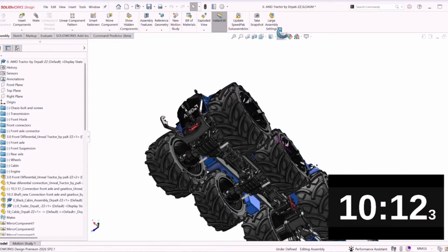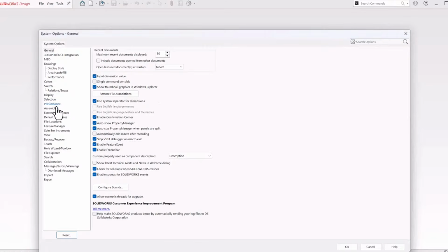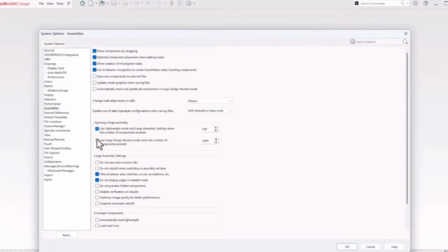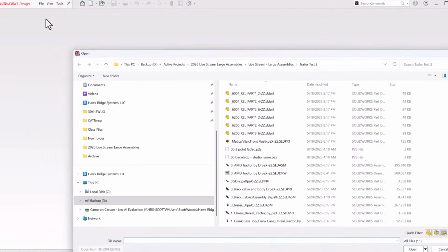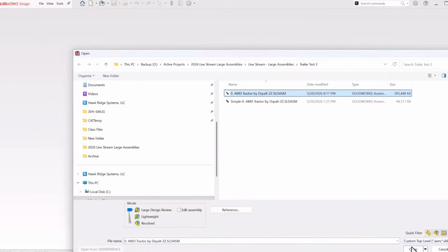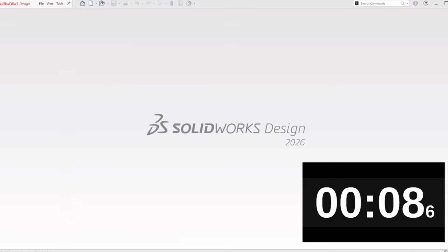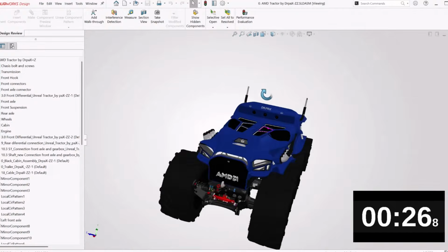So what you want to think of is that there are three elements to every SOLIDWORKS model. You have the features information, the bodies information, and then the graphics. When we're talking about some of the quicker methods like design review, that is specifically the graphics that you're going to see. It's kind of like your eDrawings viewer. Same thing with detailing mode, which will open up rapidly.